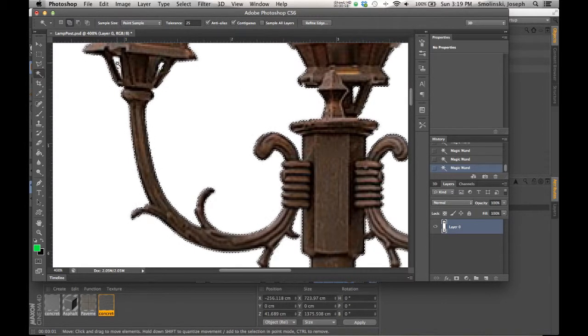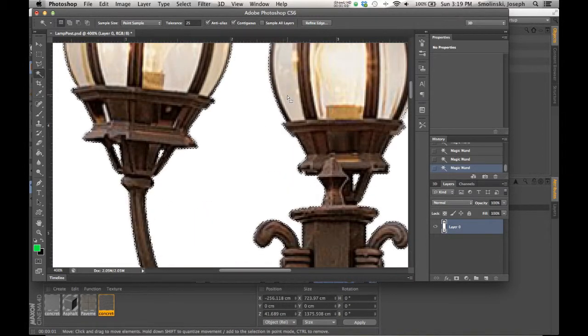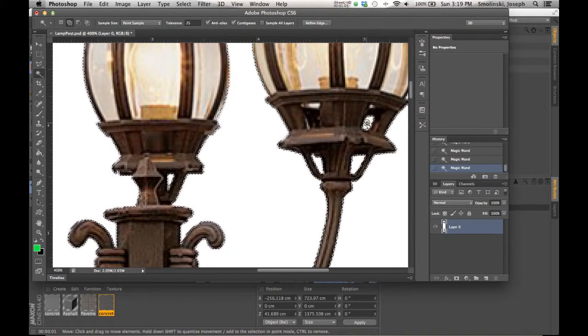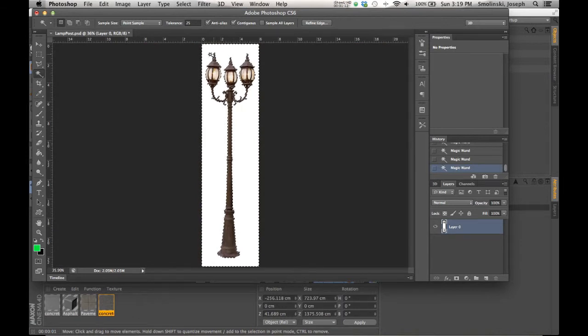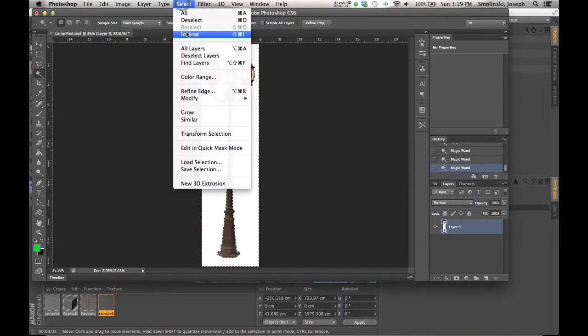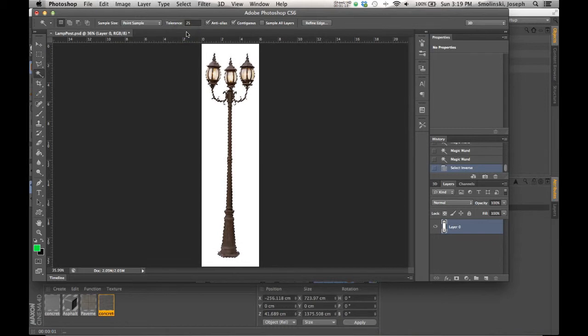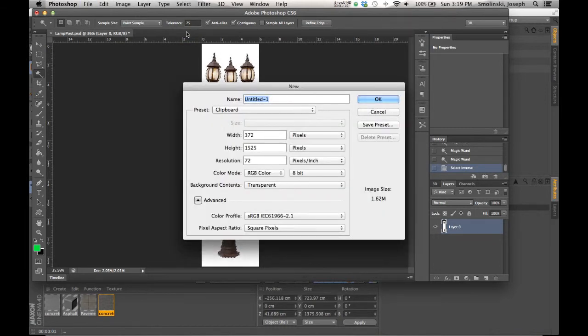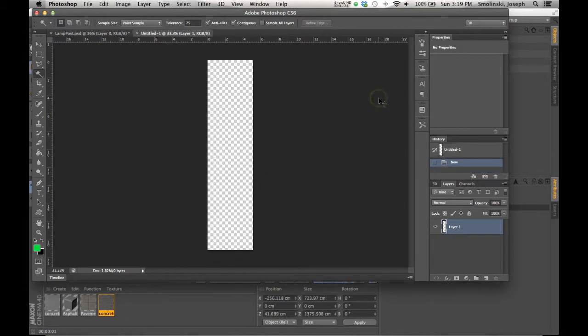So some of those negative spaces you may need to go in and correct. You want to try to drop this out. I'm just going to do this kind of quick, but to improve your projects, I would say spend some time with this Photoshop file to get a nice image with the background totally dropped out. Okay, so I selected the background. I'm just going to select the inverse. I'm going to copy this, open up a new window with a transparent background, hit OK, and paste it on here. Okay, so now I have this image on a transparent background.